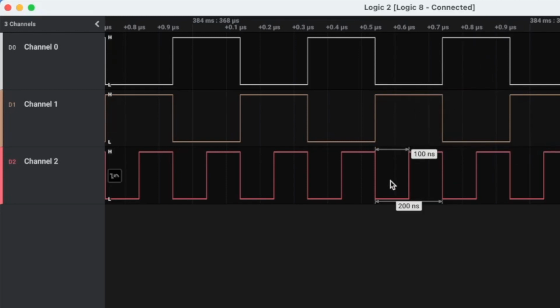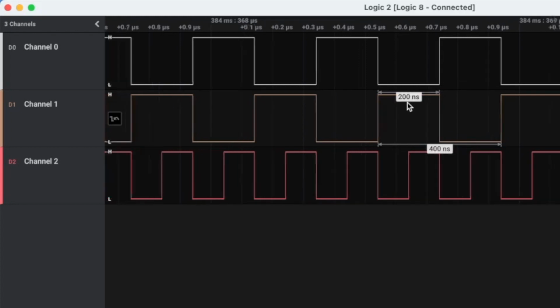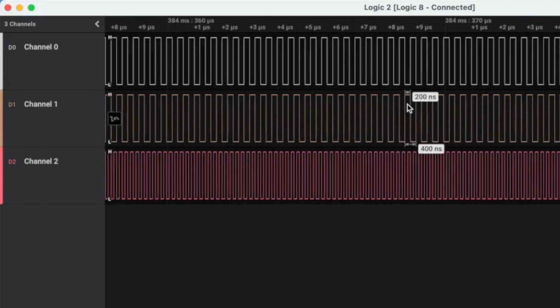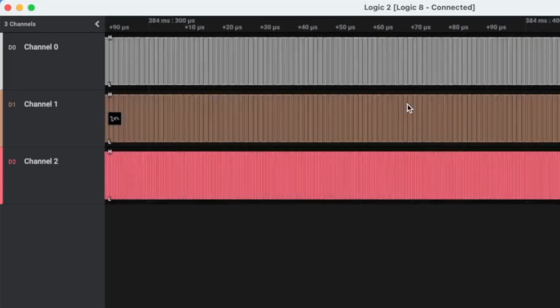And then the half clock, this is also mainly going to be used for the control module. It's going to be used to make sure we can get multiple things done within one actual clock cycle. It'll be used for like the program counter. Incrementing that doesn't take 200 nanoseconds. It doesn't even take 100, so I can do it twice in there. In that way I can access like the RAM twice and get multiple instructions. Just makes that step going to be a lot faster. So that's the reason for all of these signals.